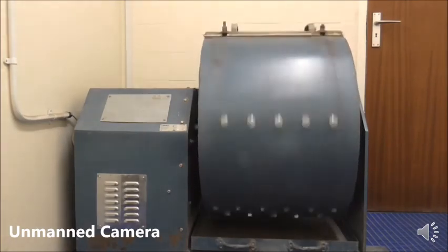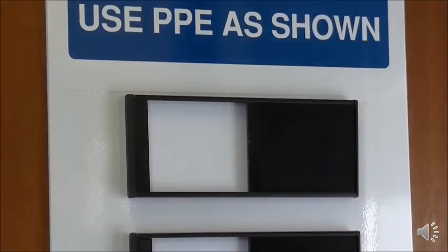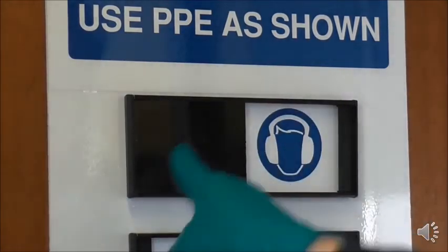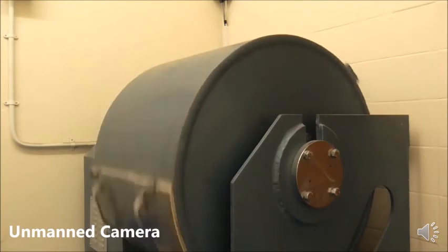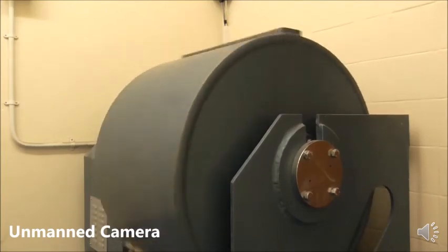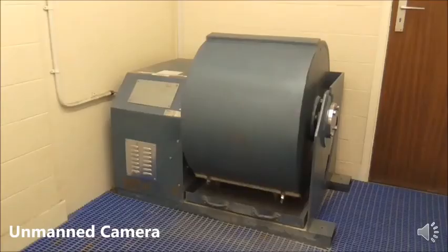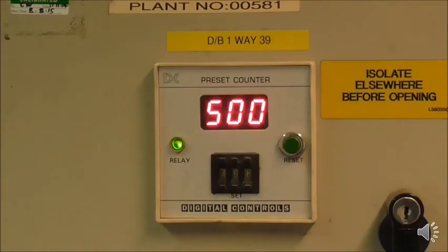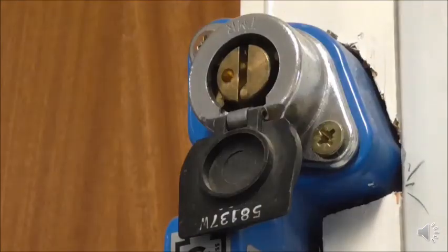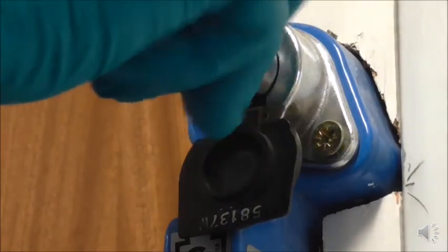So those balls are falling around and they're pounding into the aggregate, and some of the aggregate particles are, from the friction, just having some abrasion and dust is breaking off them, or they could be brittle and they could be sort of snapping in half. You're trying to see how much smaller, what proportion of the aggregate will now be smaller than 1.6 millimeters.